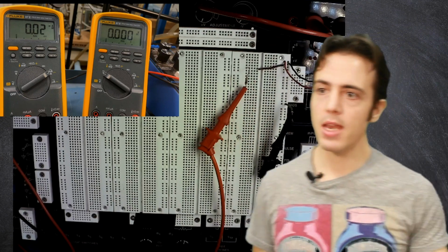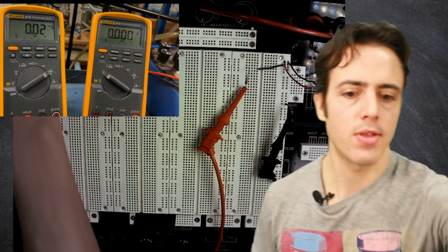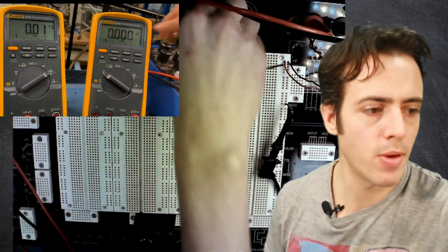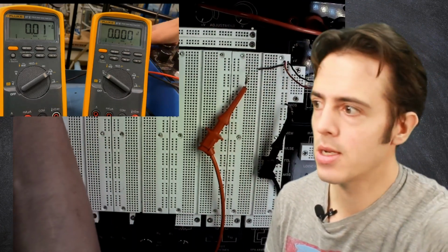We've got a 100 ohm resistor through here. So let's turn this on, and remember that both of these voltages are down nice and low. Let's just see if we get out something that makes sense. Okay, so when I turn it on, the lowest voltage that I get through is 2.8 volts. We've got sort of a voltage. It's not quite steady, it appears to be going down a little bit. That's fine. And we've got a low current coming out. So let's just see if these numbers make sense.